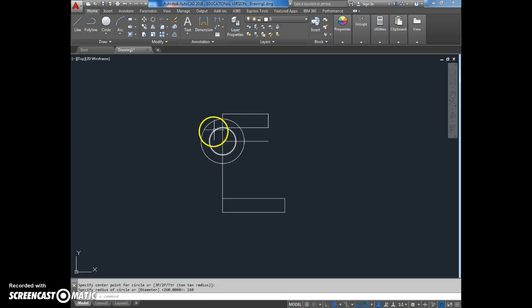And now what I want to do is draw the rectangle shape up around this area here. So what I'll do now is I'll draw that out. I'll use the offset command for this. So I'm going to click on offset. My first offset distance is 2 meters, or 200 as I have it in here. My second offset is 800, or 80. And my last offset distance is 500. My next offset distance then is 500 in the opposite plane, so 500, and I'm dropping this down to here.